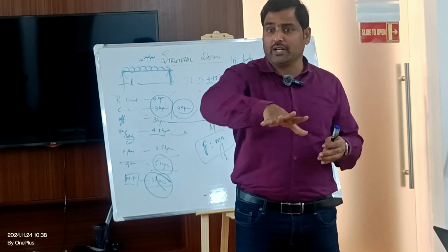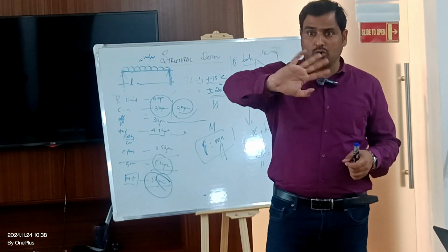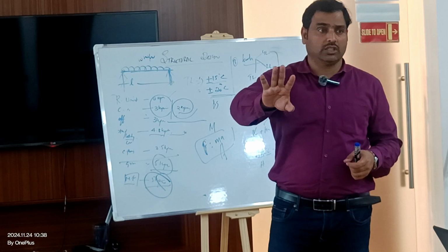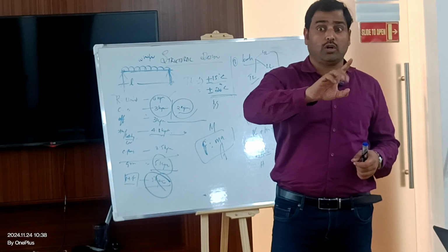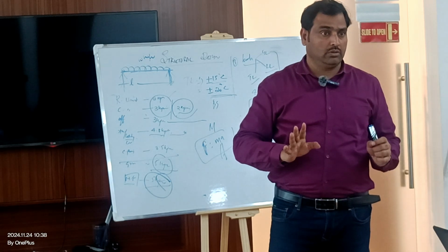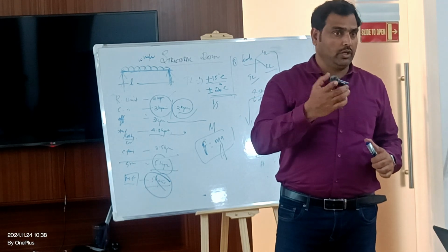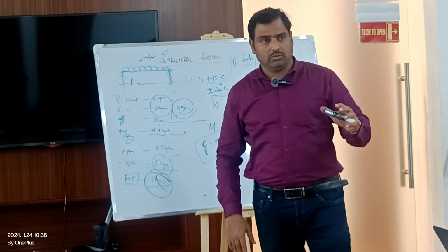Walls are going to be expanded, you don't need it. Below ground, above ground, you don't need it. Don't consider it. If you consider temperature for walls, it will give you huge reinforcement. I'm trying to help you.